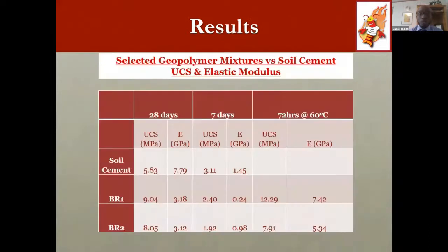So what we did was to conduct further experiments or testing on these optimal samples and compare them to the soil cement, because what we are trying to achieve with this research is to create that understanding that soil geopolymer, when applied to sandy silt soil, can yield greater strength than soil cement.